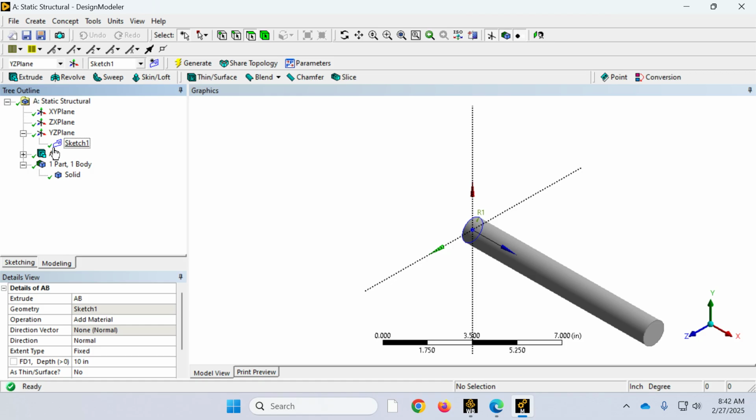When we use beams, we use add frozen for a good reason, because we want to make sure that we are able to assign a different section to each line body. But I really do not have a need for that here, so I can just continue to use add material. But first, I need to create a new sketch that has the radius of the section of BC.